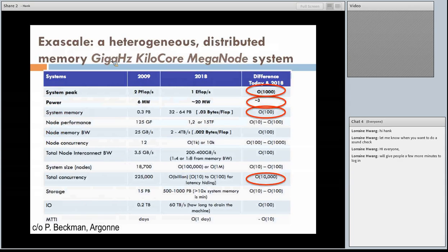This slide asks the question, if we have a gigahertz processor that takes 1 watt to power, and this can produce 1 gigaflop, what's the best way to produce 4 gigaflops? And so the idea on the bottom is that we quadruple the clock speed. But the problem is that the power consumed is proportional to the frequency cubed. And so if you had an approach like that, it would take, instead of taking 1 watt for 1 gigahertz, it would take 64 watts for 4 gigahertz.